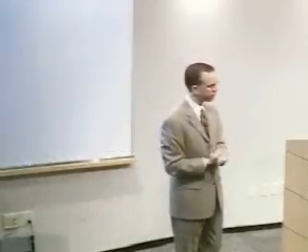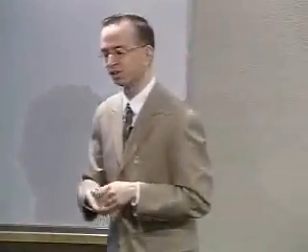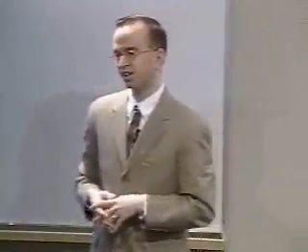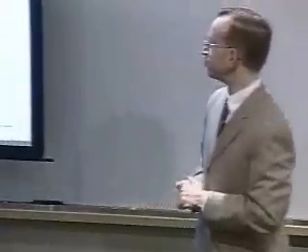Down convert to what frequency? We down convert to, well... What's your IF? So to get really technical, we're undersampling. So we have a high IF of about, right now our clock actually runs, in the actual system that's running right now, we run at 160 megahertz. And we down convert to just above that so that we can undersample. Undersampling gives us some advantages I can talk about offline. So then